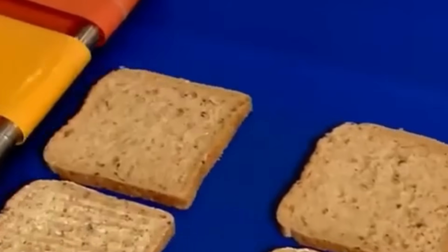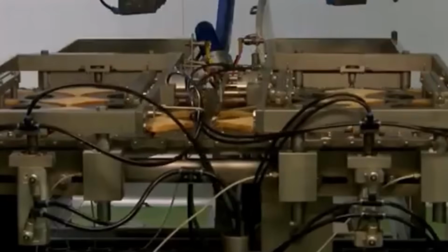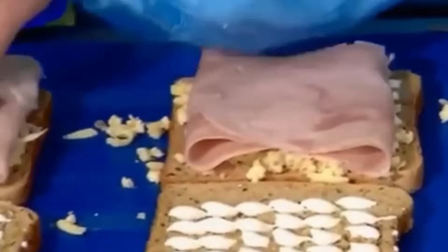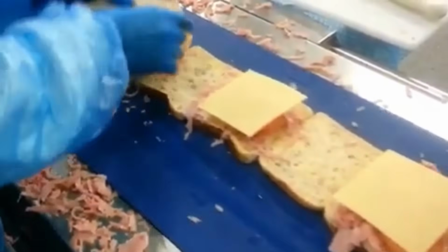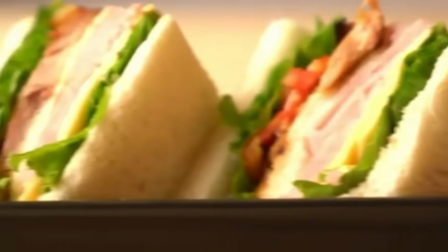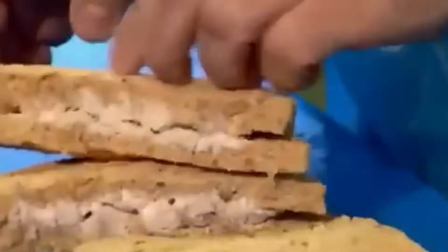For chilled sandwiches sold in wedges or clamshells, the product is inserted by pick-and-place units into pre-formed rigid plastic containers. The lid is pressed or snapped into place and sealed with adhesive label strips or heat-sealed foil, depending on product design. Transparent sections are aligned with the sandwich face to ensure maximum visibility on shelf.